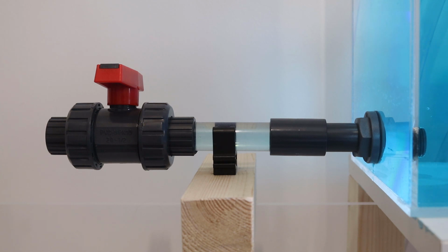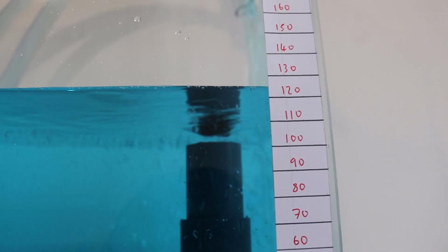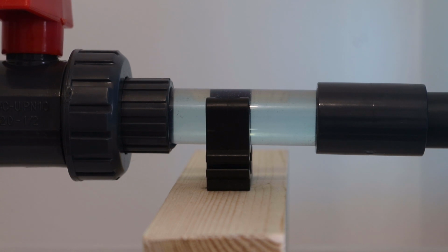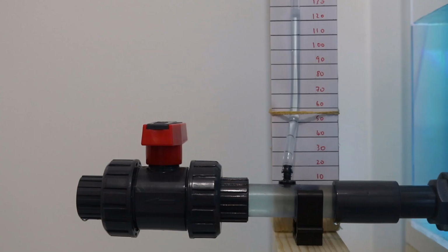In the pipe, we have 0.125 meters of pressure really trying to force its way out of the tank. We can't see the pressure in the pipe as easily as in the tank, as here the water can't find a free surface like it can in the tank. But we still have that 0.125 meters of pressure pushing against the pipe wall. We could actually see this pressure if we were to drill a hole in the pipe and install a gauge. The water would now find a free surface in the gauge and show us the pressure in the pipe, which is the same as the pressure in the tank.